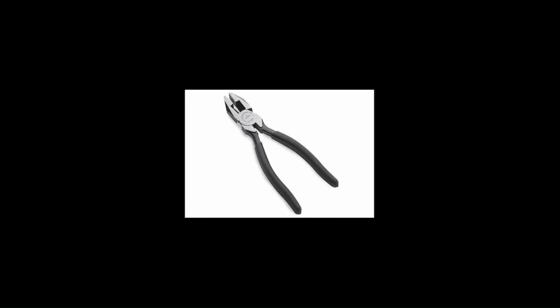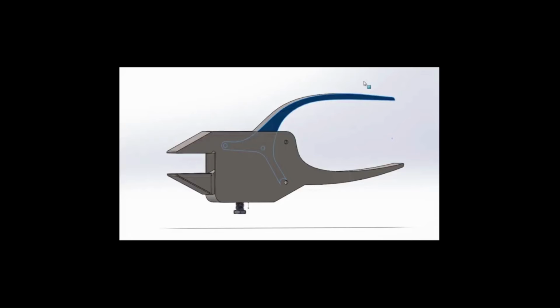Conditions to get parallel crimping surfaces of the jaws are: the first condition is that for each jaw, the distances to the clamping surfaces from the center line of the slot and from the center of the hole should be equal, and the second condition is that the center distances of the holes from the handle are also equal.